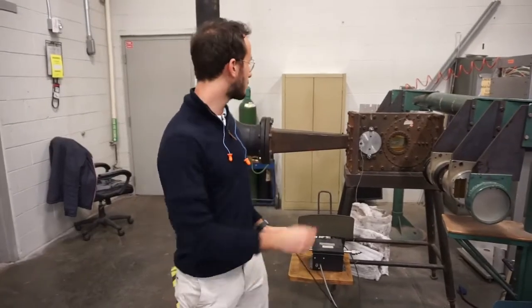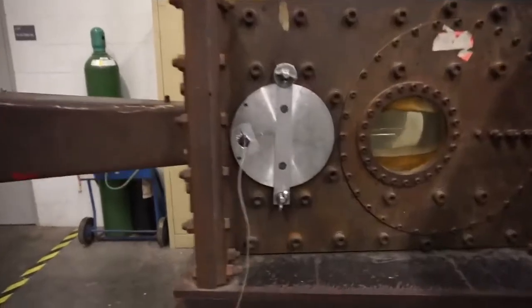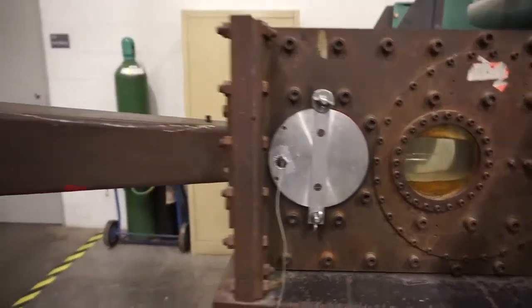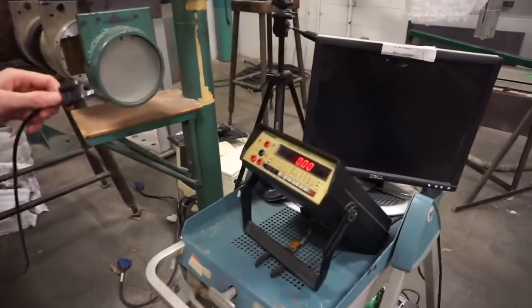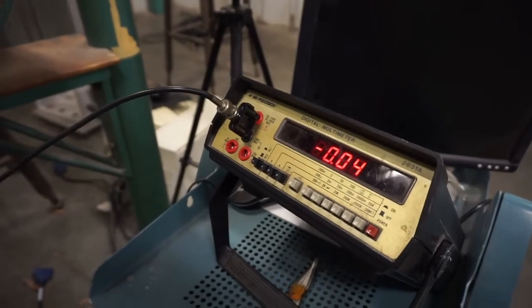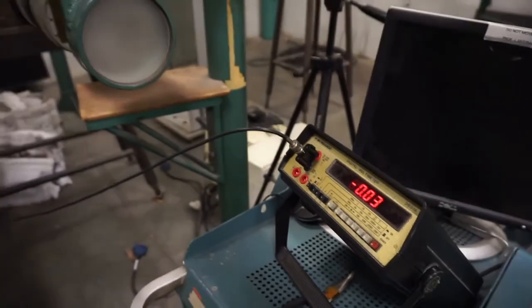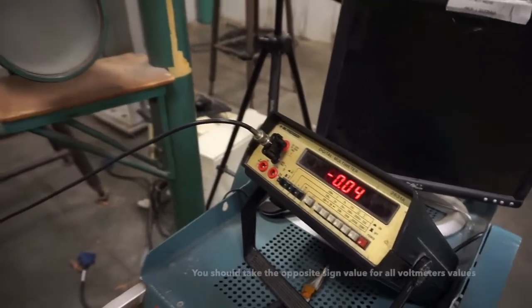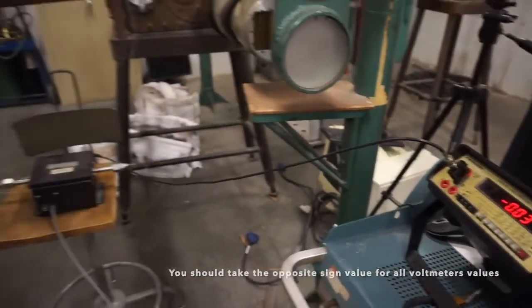So now we've just put the pitot probe inside the blowdown tunnel, so we'll record the stagnation pressure first using the voltmeter right here. We'll connect the baratron to the voltmeter. When there is atmospheric pressure on both sides of the baratron, the value is 0.04. So it means negative 0.04. You need to take that into account in your future calculations.